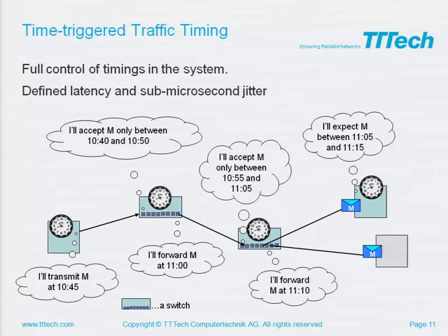Here, for example, the precision of this window depends on the synchronization precision. So this means I can establish a higher granular clock on which the scheduling is based, and this higher granular clock depends on the precision within my network. Typical precisions here are in the area of 100 nanoseconds, for example, depending on your setup.